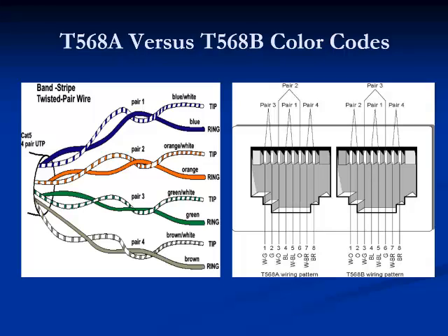The T568A configuration is partially compatible with an older wiring scheme called USOC, which is commonly used for voice systems. Be consistent at both ends of the horizontal cable. When you purchase patch panels and jacks, you may be required to specify which pattern you are using, as the equipment may be color-coded to make installation of the wire pairs easier. However, many manufacturers now include options that allow either configuration to be punched down or connected on patch panels using jacks.